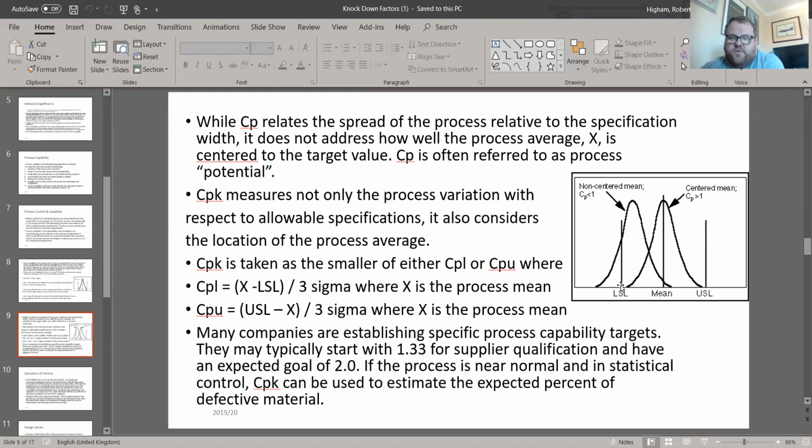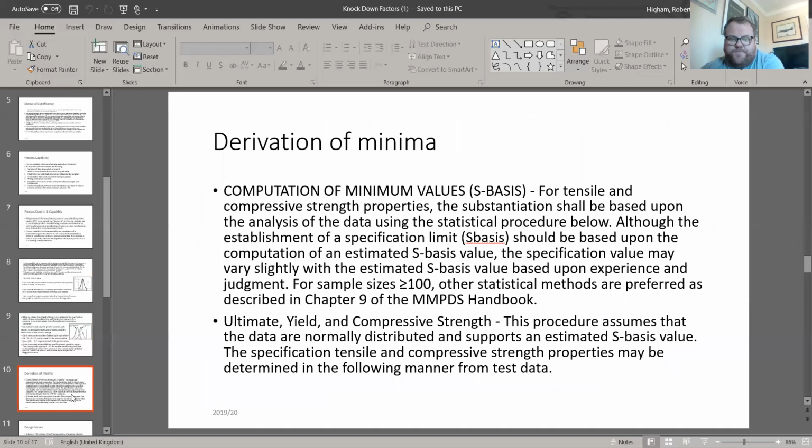So for your assessments where you've been given some data and you've worked out mean and standard deviation, what you could have started to do is plot what these graphs look like. Now, you didn't have enough tests in the end, so you didn't have enough data points to do it fully valid, but that's the start of the process. If we had a brand new material that we didn't have a spec limit for, the way in which we, in industry, actually calculate the minimum isn't as simple as just 3 deviations, because 3 deviations doesn't factor in the knockdown of quantity of data appropriately.